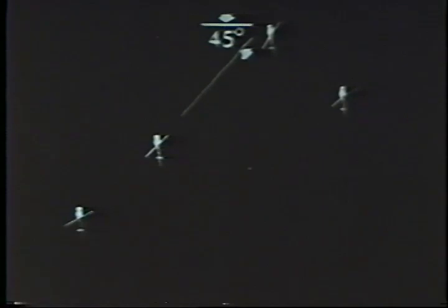The last formation we'll discuss is the tactical heavy formation. This formation can be formed either left or right and is composed of two helicopter sections. In a tactical heavy left, the flight leader and his wingman form the first section with the wing flying 45 degrees astern and to the right of the leader. The second section is composed of number 3 and number 4, 45 degrees astern and to the left of the leader. Number 2 and number 3 fly a 3-foot vertical step-up on the lead, while number 4 flies a 3-foot step-up on number 3. Spacing between sections must be sufficient to permit the wingman of the flight leader to move from or to either echelon position.